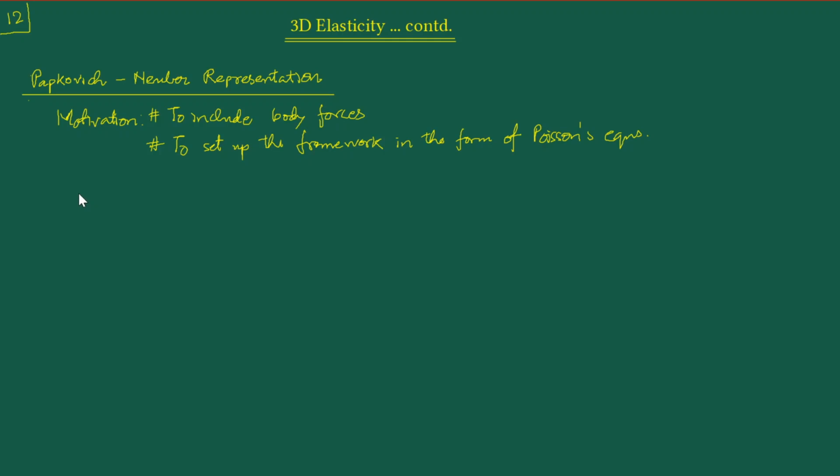So this here already is a major difference from the route that we have been following in the previous displacement potentials, where I just wrote down the forms of the displacement potentials without actually going through any preliminary steps. So here we are going to discuss the preliminary steps involved in that representation of the displacement vector in terms of this Papkovich-Neuber representation.